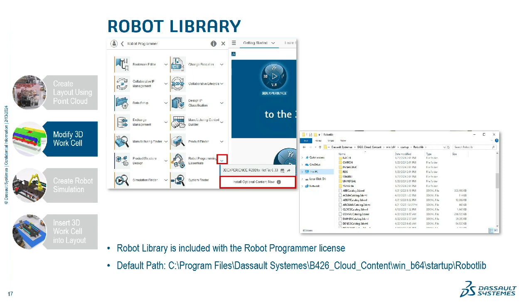You have your folders, which you can actually go into, and they can download individual robots. Any of the 3D XMLs on that top level, if you import those, you'll be importing the entire robot library of that type. So if you want all of the ABB robots that DELMIA has in its library, go ahead and import that one. If you just have a specific operation, go into one of those folders and find the robot that's appropriate.